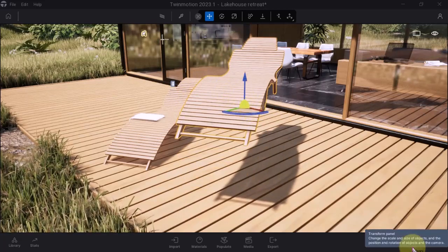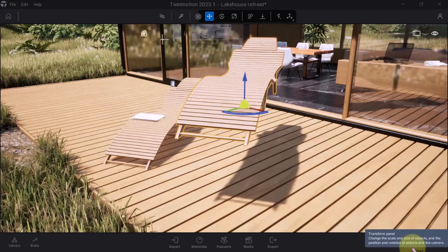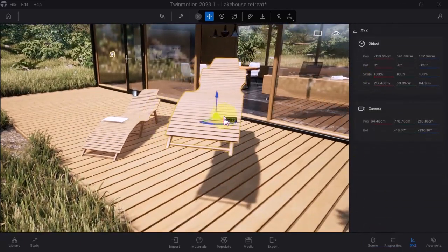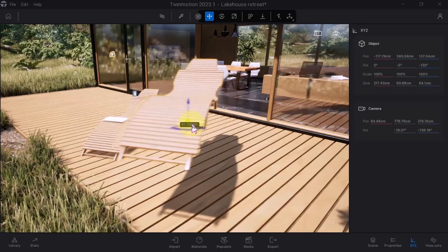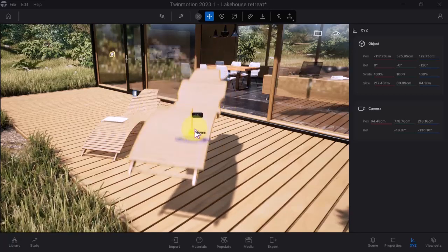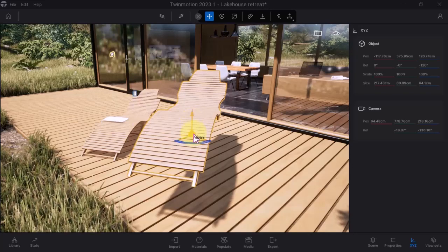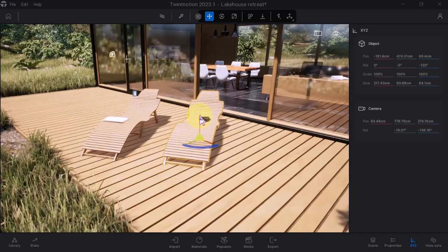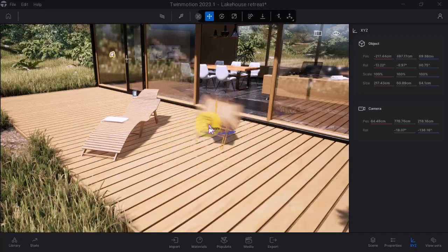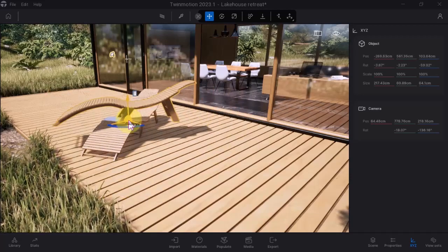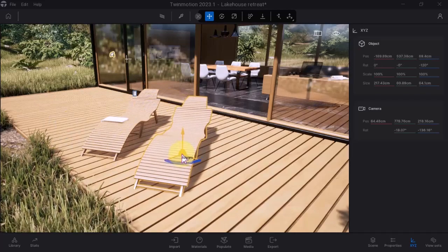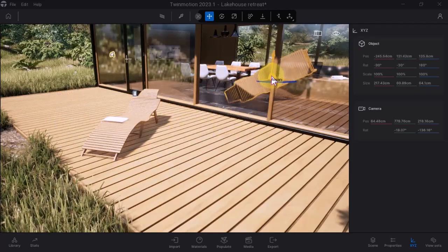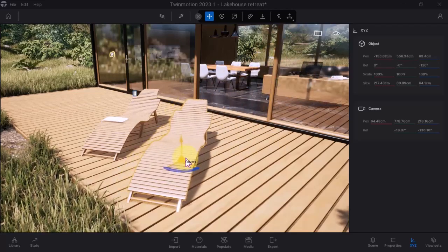And let's take a look here. We have this X, Y, Z transfer panel, and as you can see, we can change the coordinates with these options here. And if you select this middle section here, and when you start moving it, it is moving in all directions, and considering that these objects are face-based, they will automatically set on any surface.